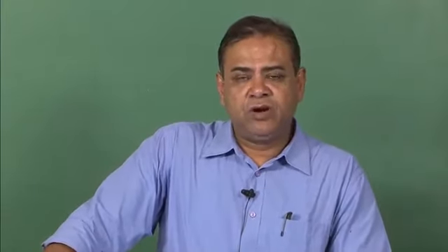Now in this lecture we will try to see what other information the phase diagram will not be able to give us, and what things we need to consider to know other aspects like the morphology of the phases, or what happens if we change the cooling rate. For example, till now we have been talking about equilibrium, but actual operations do not happen all the time in equilibrium, and whenever we have an equilibrium process, that means we have to give sufficient time at a particular temperature to reach equilibrium.